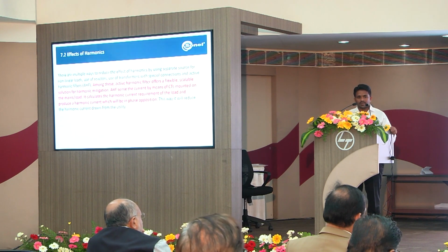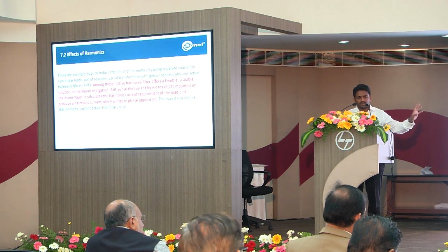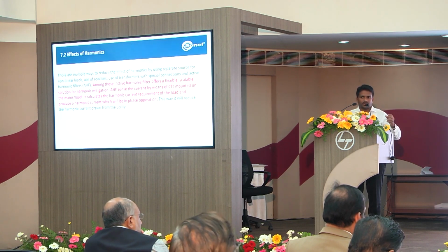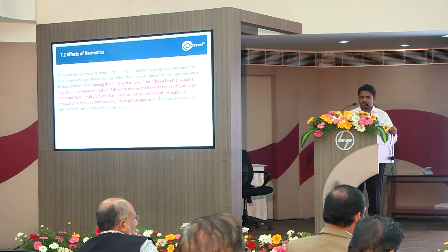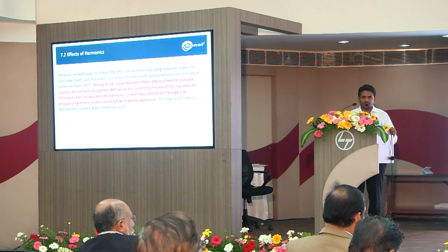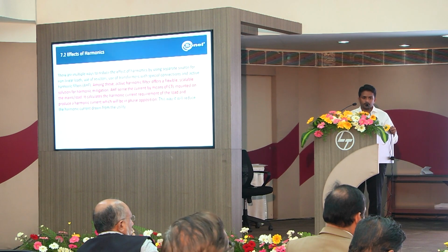This is also taken from NEC 23 only. A few suggestions: whatever is highlighted in red is exactly a copy-paste from NEC. They have recommended it, it's not a product standard as was mentioned before, but just a suggestion. Using an active harmonic filter is suggested in NEC 23 to improve power quality.